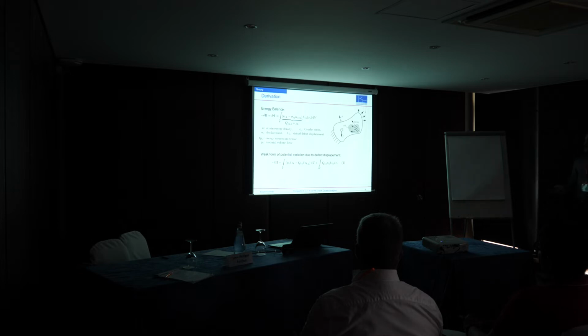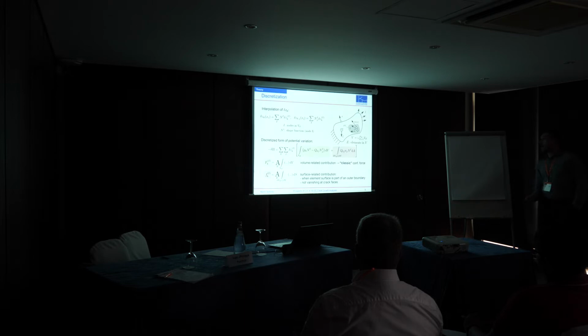What we can do with this formulation is perform straightforward discretization in terms of the finite element method to use this in finite element frameworks. So we perform interpolation of our test function. This is nothing special, and we obtain a discretized form of our potential variation, where we see that there are two contributions to the force that drives the defect displacement. The first one, indicated here in green, is a volume-related contribution.